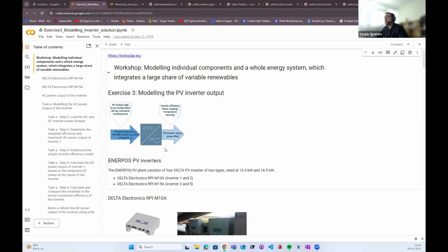The other thing that can occur on an inverter is clipping, and that is true especially if the input power, so the PV array, is oversized. So we have a 5 kilowatt PV array and a 3 kilowatt inverter. Of course, the inverter will not output 5 kilowatts, even if the panels can generate that. Those 2 kilowatts are being clipped, and those we consider to be losses.